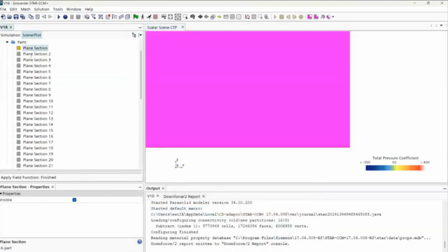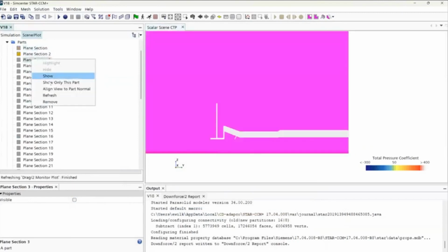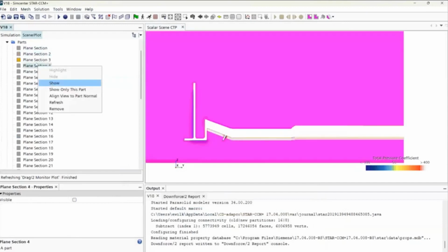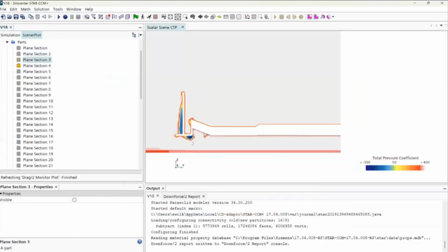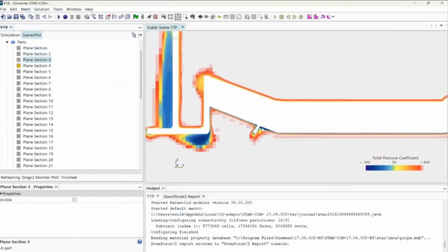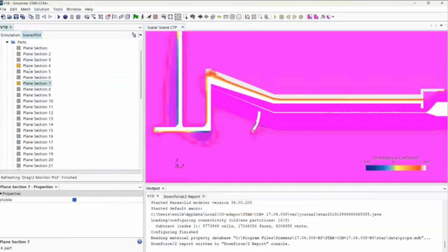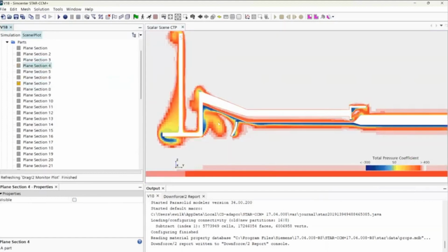You can go through each single plane and look at how the air flows around. So ambient is white. As you hit your geometry, you get separation here, and you can visualize the flow. If we keep going, we now have some sort of system here. We have separation here a little bit, and then as we go on, maybe we're spooling up a vortex here,